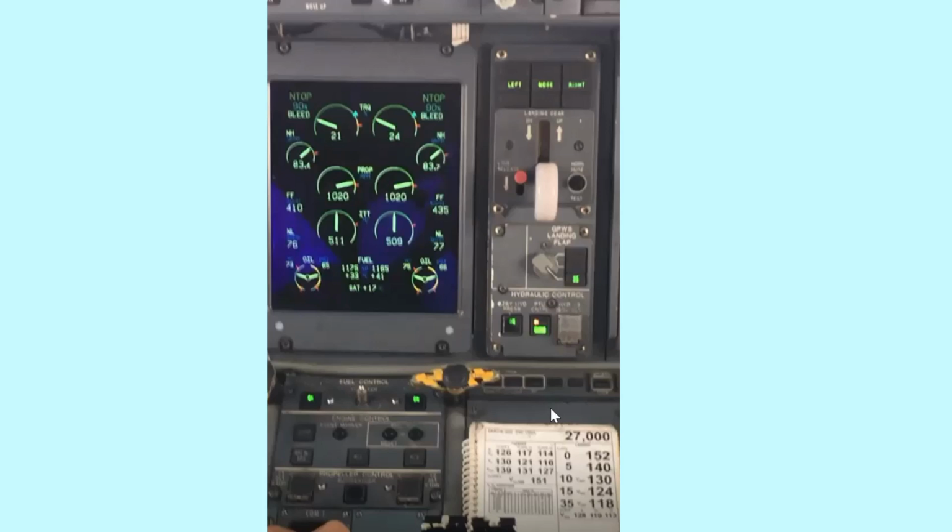Now I'm answering the question, why is this so-called magic number set? It is not a magic number, it is what the aircraft actually does. And how do we know it? We know it if we keep the autopilot engaged until 1,000 feet AGL. Once flaps 35 is deployed with autopilot, the nose will start pitching down, as you can appreciate, because when you deploy flaps you are increasing lift, but the aircraft wants to pitch down, so the autopilot says, no, I'm not going to go up, I'm going to pitch down.